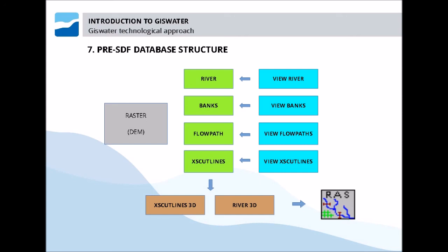In the case of HEC-RAS, at the moment, we are only at the pre-processing stage. For instance, we can only import a geometry into HEC-RAS, but under no circumstance can the results be returned to Giswater. Anyway, HEC-RAS has a very powerful tool to see the results of post-processes, and it does not make any sense at the moment to return the data back to Giswater.